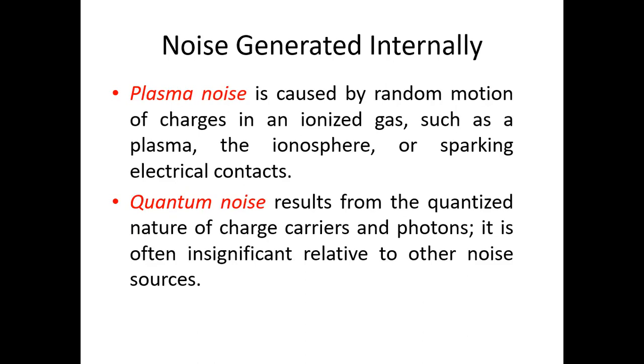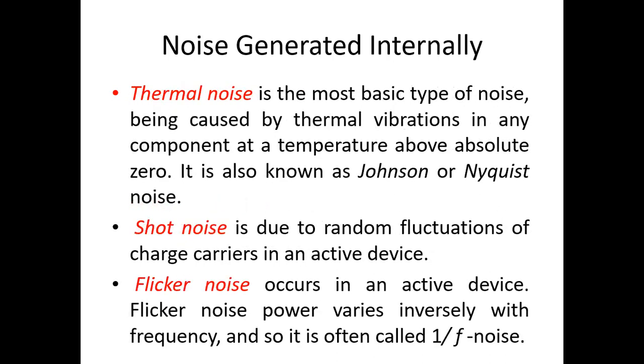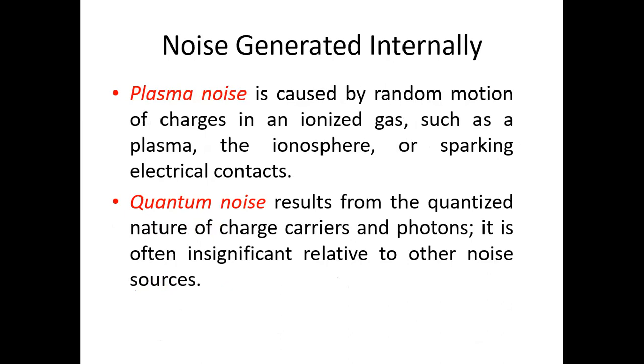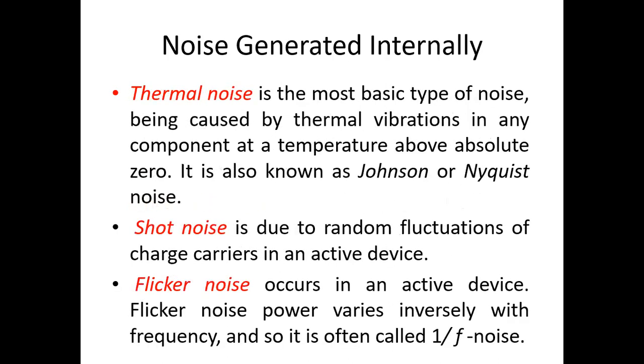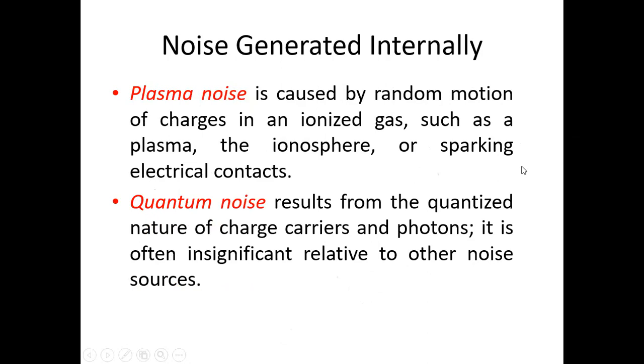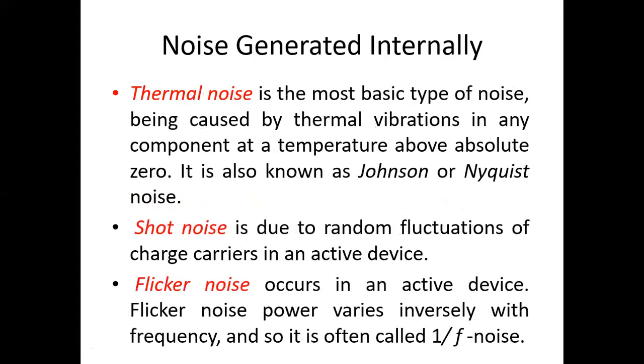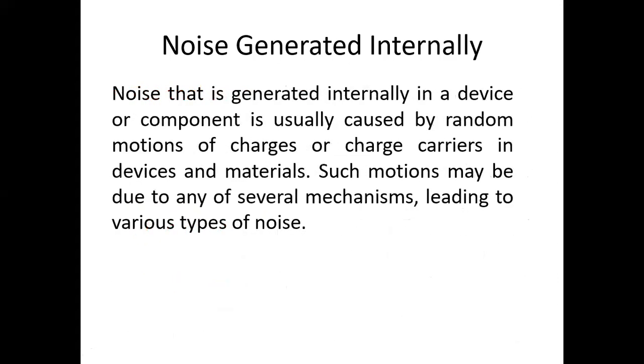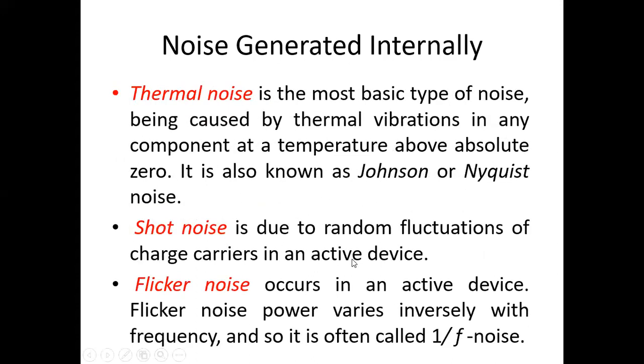But the noise of these later types, from shot noise through quantum noise, either doesn't exist everywhere, or is very low in power. So mostly you need to consider the thermal noise. The other noise types are either absent in your particular circuit, or the part of the circuit that you're considering, or they are very low. The thermal noise itself is not high, but it can be significant when your desired power is low, while other noise powers may still be insignificant.